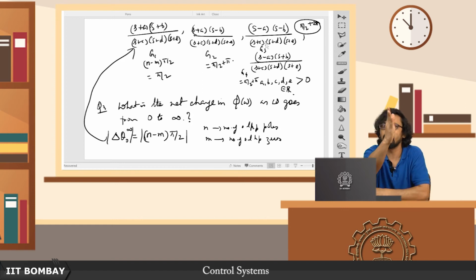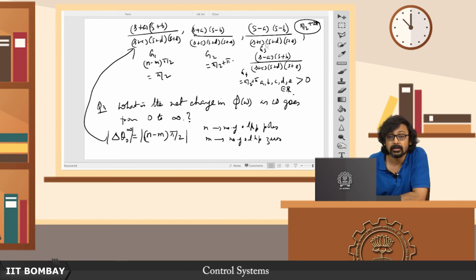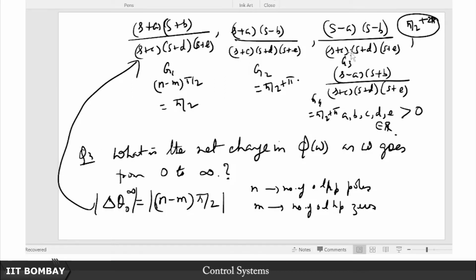Just look at the magnitude plot, look at the corner frequencies, and those are your poles and zeros, right. So that's why it's easier to deal with minimum phase systems when identifying systems also. So now I hope you understand why you have certain systems which are qualified as non-minimum phase systems. Yeah, so that's a point that I really wanted to highlight.